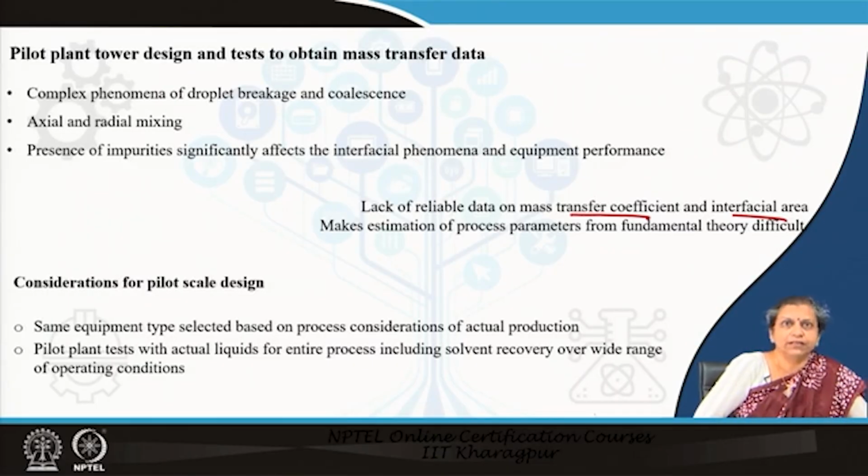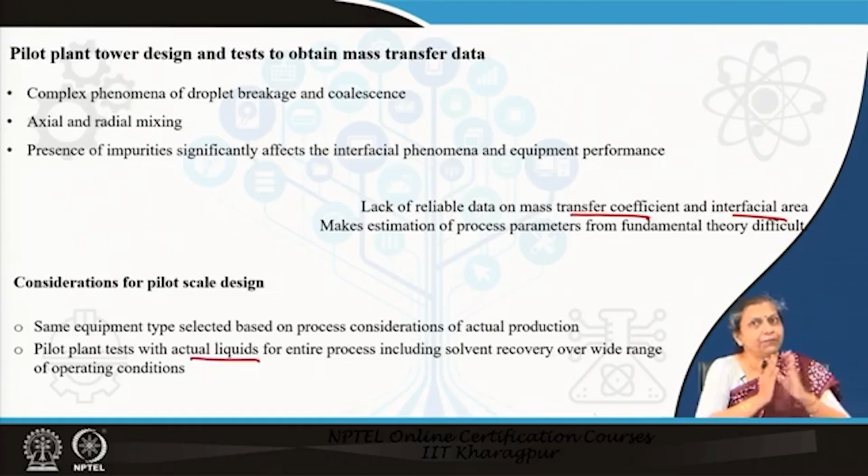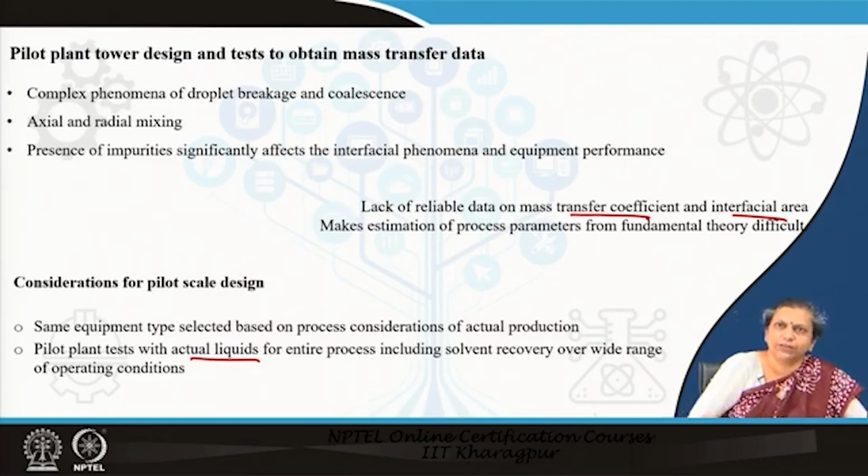And the other important thing is the selection of solvent. Frequently we find that we select a solvent and for the pilot plant test we perform these tests with a synthetic fluid which has the same properties as that of the actual solvent. This often results in unsatisfactory results. So, therefore, it is important for you to consider that the pilot plant tests are also performed with the actual liquids, and when we are performing pilot plant tests, we should be performing both the extraction as well as the solvent recovery over a wide range of operating conditions.